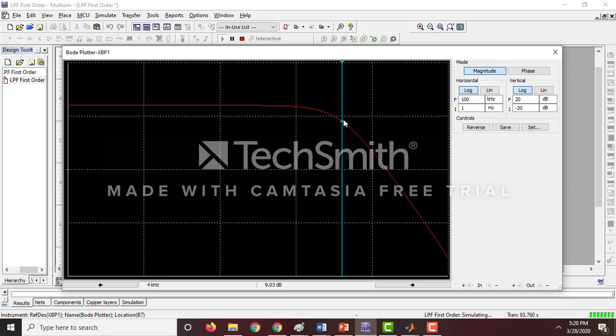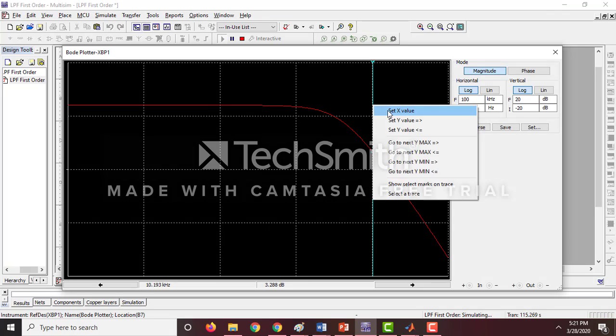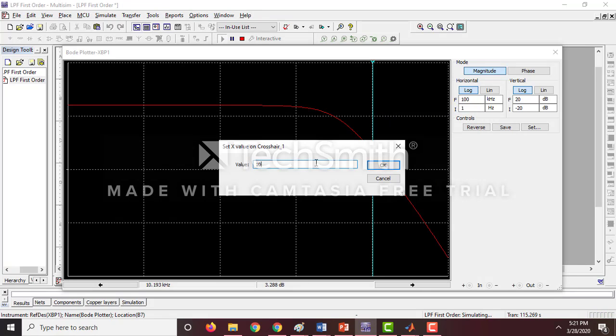So this is the cutoff frequency and this is the bandwidth. Up to 4 kilohertz the signal is actually passed, whereas for any signal after 4 kilohertz the gain will be drastically reducing. Clear? Here one more thing you can see: let us take the case when it is 10 kilohertz.